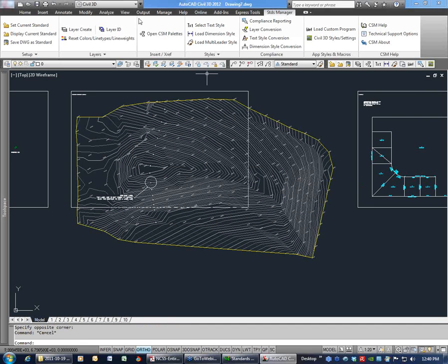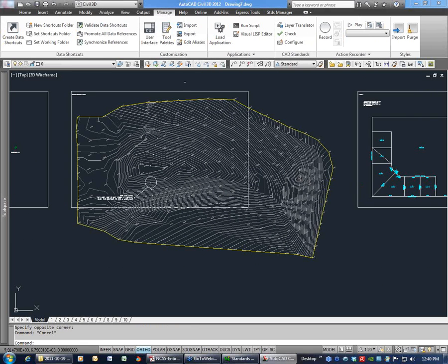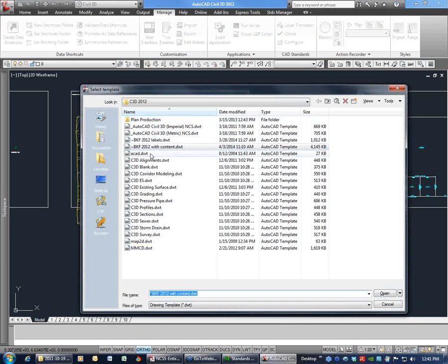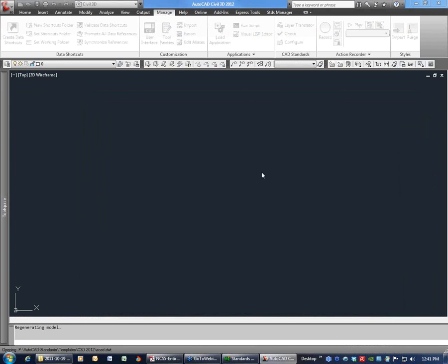Okay. So Mark just wanted to make sure that you guys knew what was going on with the templates. And last but not least with the templates, if you open a drawing that has not touched Civil 3D, or if it's an old drawing and you want to get your styles from another drawing, there are a few different ways. One is to just drag and drop, but it's just one at a time. For example, let me just do this. I'll do it with you here.